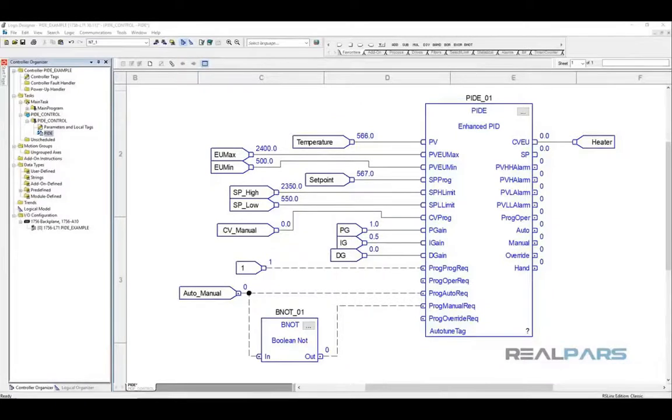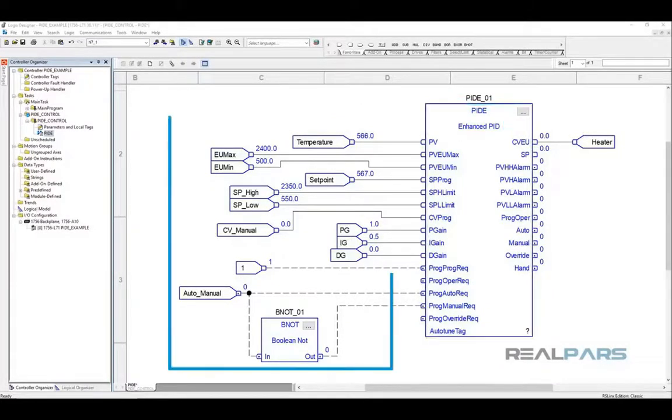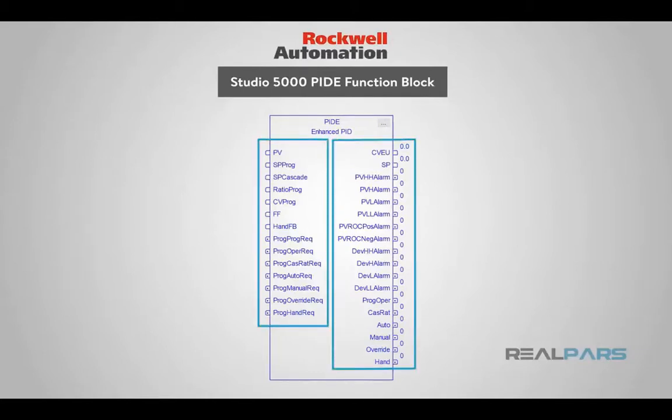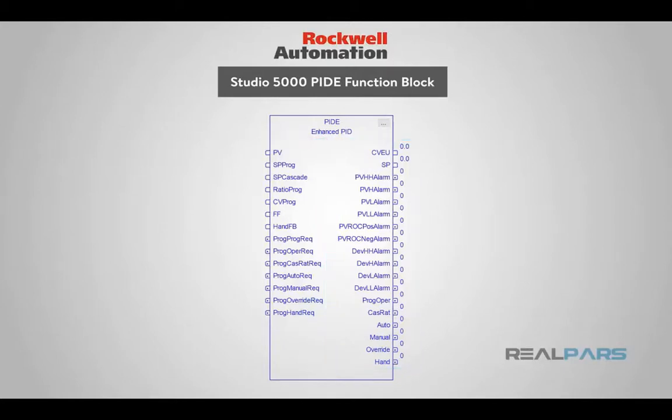Function block programming uses diagrams with symbols to represent functions and input and output connections between functions. While at first, this function block can be quite intimidating, it shares similarities with the standard PID instruction, and you'll only need to turn on parameters required by your control program. In this example, we will basically get you off the ground using the PIDE instruction and the program options essential to get it working.